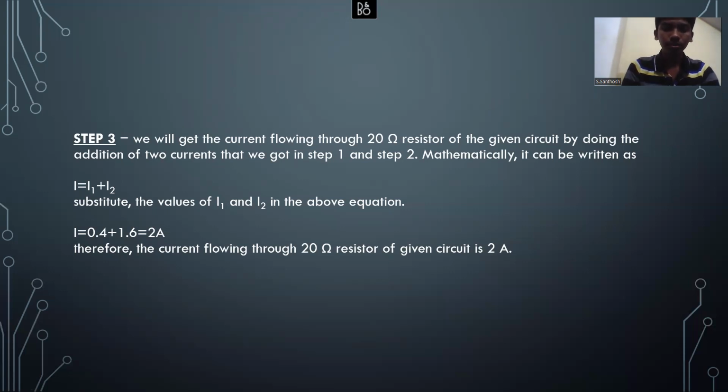As I said before, we'll be using these theorems while solving any circuit that has more than one voltage source or more than one supply source, energy source, in the circuit. And we solve it by taking a short circuited voltage source and an open circuited current source and then adding them up. Over here, if you have any doubt with the calculations, you can also use other theorems and calculate it so that you can cross verify and find out whether your answer was right or not. So thank you. That is all about the superposition theorem.